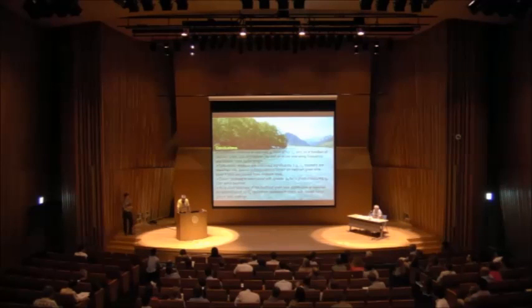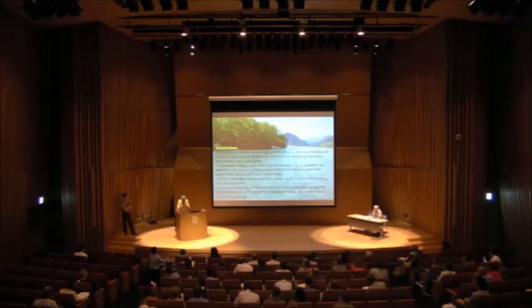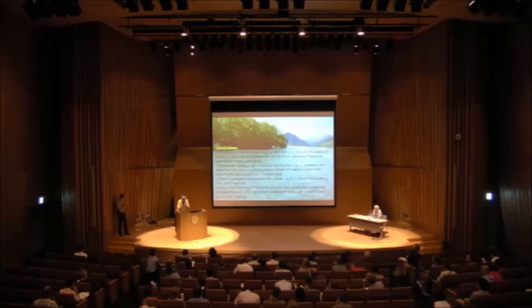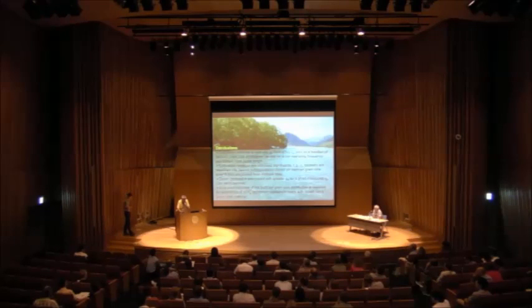Yeah, it's a good question. I don't know if I properly respond now to your question, but we have had some observation when we started with more systematic flume experiments. First, we fixed our plate almost in the middle of the entire flume length, and we noted after some time that too much of the vibrations were transmitted from the entire flume that also started to vibrate. So in a second step then we physically separated the plates at the downstream end from the flume.